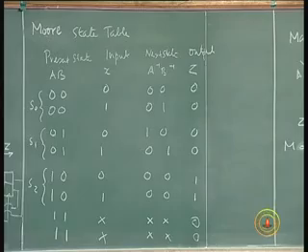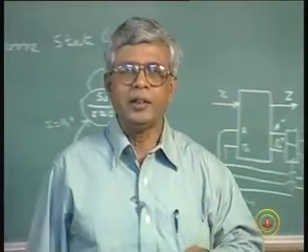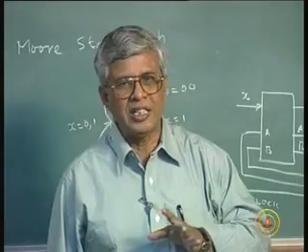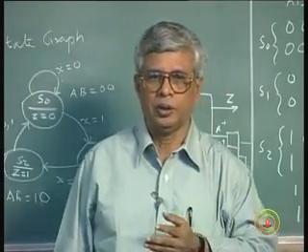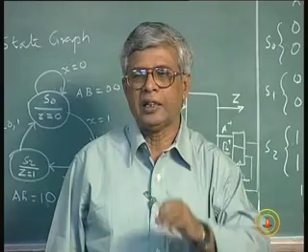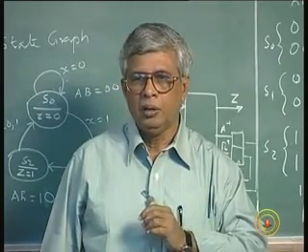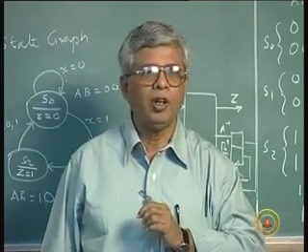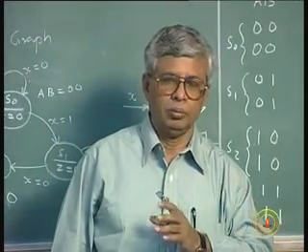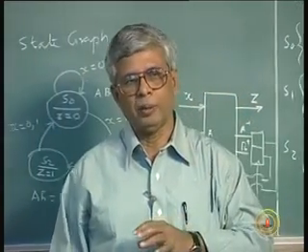So an input-output condition is also important in the design of a state machine. Outputs are important because outputs need not always be the state outputs. State variables will tell you the state in which the circuit exists at that time, but may not give you the indication of the outputs. The outputs may be independent or different from the state variables.